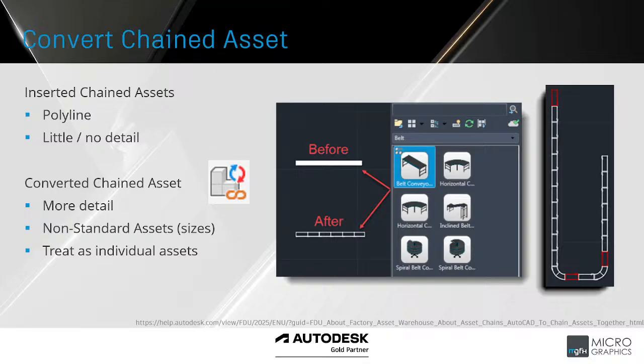Then on the right-hand side, we can actually see some red assets there. These are those fillers. These are the non-custom sizes. So basically, starting on the right-hand side, a full-length conveyor belt. We get to the filler at the bottom right. This is working clockwise, as I mentioned before. And then it places the standard corner, a standard conveyor, then a custom length once again. So you'll see working in that clockwise direction, the custom length is always added before the corner. But we now have those individual pieces to get a full bill of materials on how many conveyor segments we need.